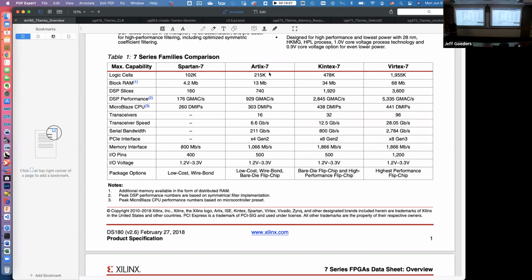I have here in my notes the ratio between the number of logic cells and 6-input LUTs is 1.6 to 1. See, so they're continuing to quote them in their old logic cell numbers. So you can compare series 7 to series 6 and 5 and what have you. But they did make a change at some point. So you got to be aware of that.